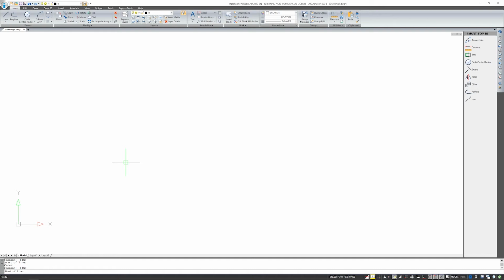If you have this box at the cursor enabled, input is relative. So you do not enter absolute coordinates from point 0, 0, which is denoted by default in the lower left corner here, but from the point where you click. If you wanted to start drawing as absolute, you have to turn this box off, which I'm doing now.